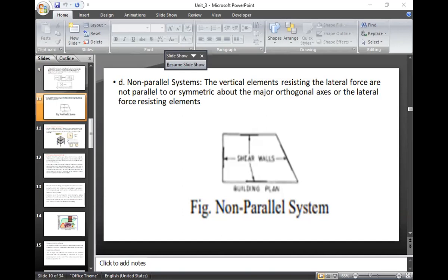We have to reduce the torsional rigidity and the re-entrant corner effect. Again, there should be some rules about the openings in the building, which should be followed by every story for achieving regularity in the building. And a non-parallel system also becomes one of the irregularities in the structure.